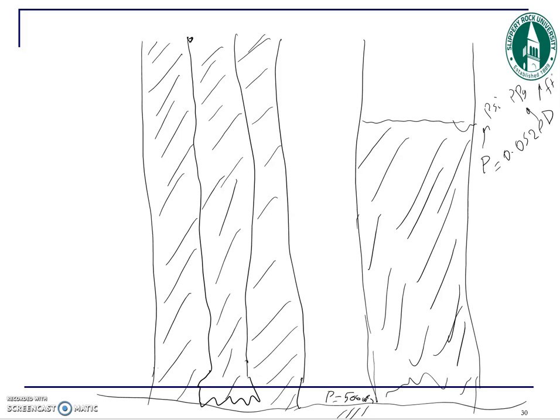So if that pressure drops below the formation pressure, then a kick happens. So you need to be careful about this situation. You need to consider that if you are taking out the whole system, the pressure of the formation that exists at the bottom is still lower than the hydrostatic pressure of the drilling fluid that you have inside the wellbore, correct? So now the displacement comes into play. This volume that has been displaced, this drop in volume, is called displacement.